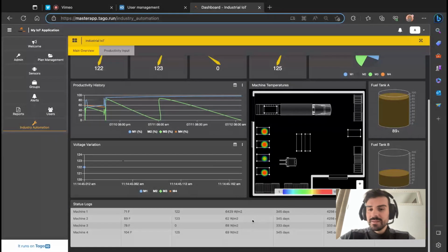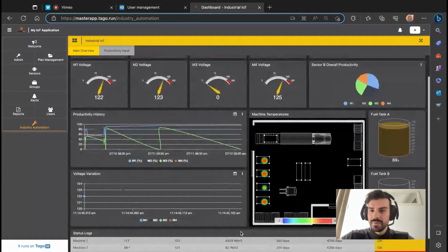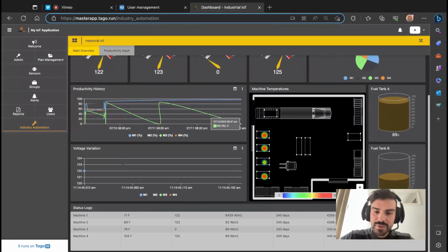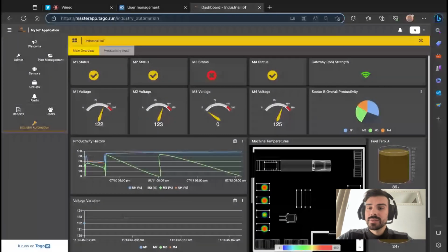So once we detect the vibration, we can make an algorithm that will let us know, for example, what the productivity is on that particular machine, right? Is it working at 100% of its capacity? Is it producing as much as we wished for? Or for how many days has the machine been running, right? And when will be the next maintenance? It gives us insights on the productivity.